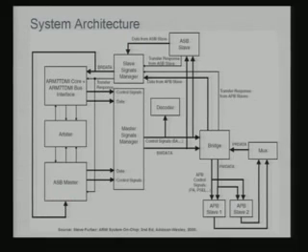Now, if you look at the complete system architecture, it would look something like this, and you should note this carefully, because it tells you how a complete SoC architecture internally would look. Again we are looking at using ASB, these are all ASB masters, and this is your ARM7 core, which would communicate with your arbiter.